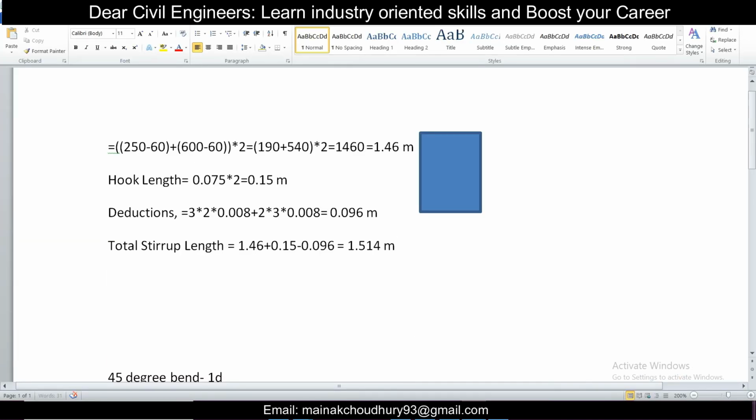So the number of stirrups in a beam span of 1 meter will be equal to 1 divided by 200 center to center distance, 0.2, plus 1.